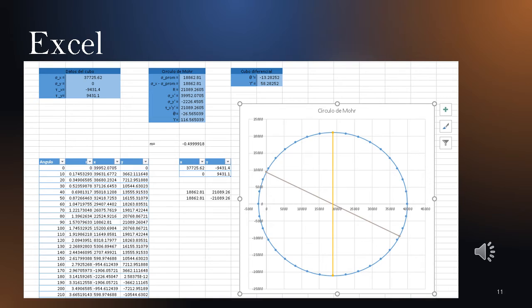These values made the Mohr circle in the graph. To graph the lines that connect the normal and shear stress, we only needed to select the values given to us by the problem and add them to the graph. This also worked for the maximum shear stresses.